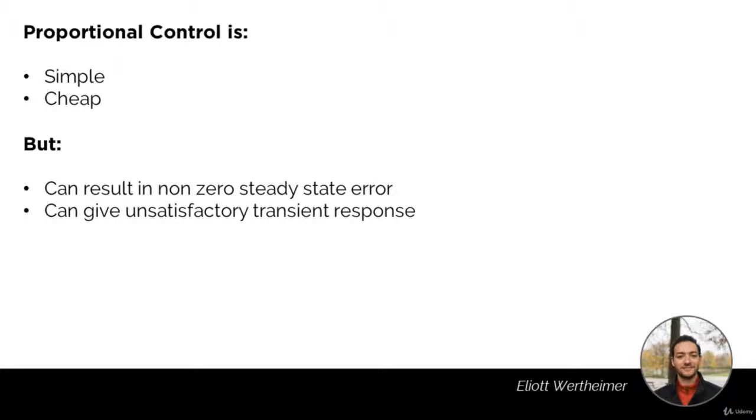So it leaves it lacking, but it's also the most simple way to implement a feedback control loop or a closed loop control. If you were to compare it to a mechanical component, a proportional controller is actually a spring. If the error is too large, it will immediately pull back on it to make it smaller. But if the error is too small, then the spring will barely move and won't be able to compensate for that error.